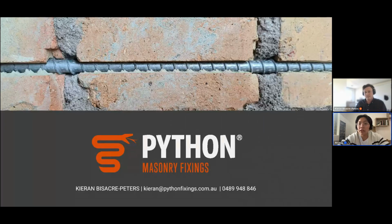All right, so we've got another question from Bilal. What is the best method to check the masonry wall ties if the rusty tie is embedded under the brickwork? Yep, that's a good question. The best way to do that would be to implement a program where you systematically extract a certain number of bricks across various locations, particularly if you think it's lime mortar where this problem might have occurred. So I'd take a sample of bricks out in different locations across the site and inspect the condition of the ties in the mortar joints.